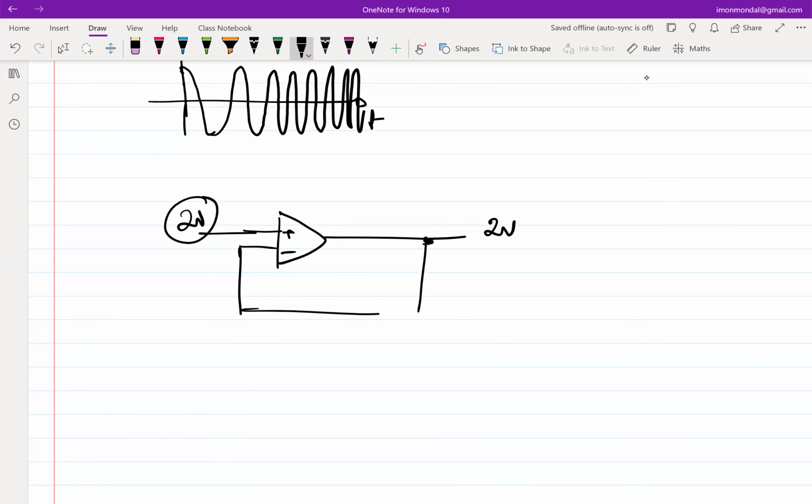And that is what we typically use, and they are called crystal oscillators. Their center frequencies are extremely reliable. And when I say extremely reliable, if you tune it to probably 10 megahertz, they are going to probably shift by 1 ppm across maybe a few minutes or so, right? I might be misquoting some numbers here. Chitra, can you back it up? Okay, right. So I underestimated its accuracy. It's basically extremely reliable.